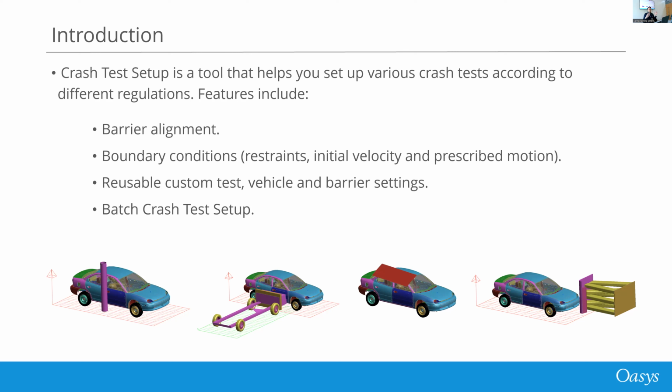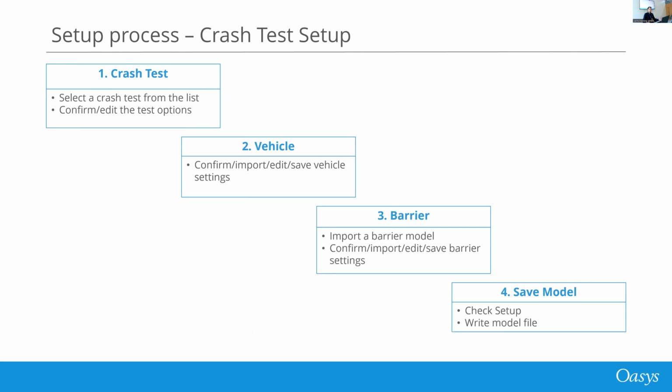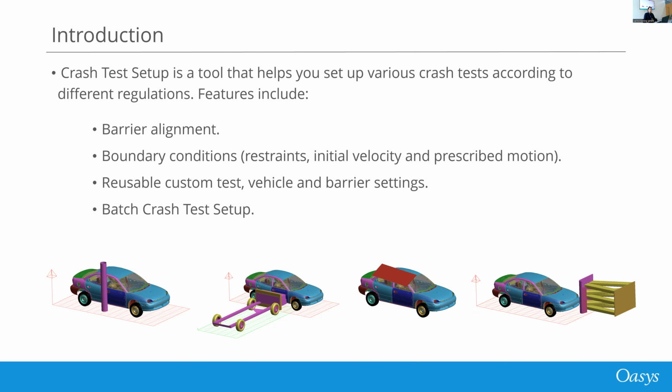You can create your own custom tests, and you can modify vehicle and barrier settings to create your own bespoke load cases for your vehicle. These settings can be saved and reused, making it really easy for you to set up your custom crash tests straight away right out of the box. Now, the tool can be used to set up one crash test relatively quickly, but it's also designed to set up multiple crash tests in one go